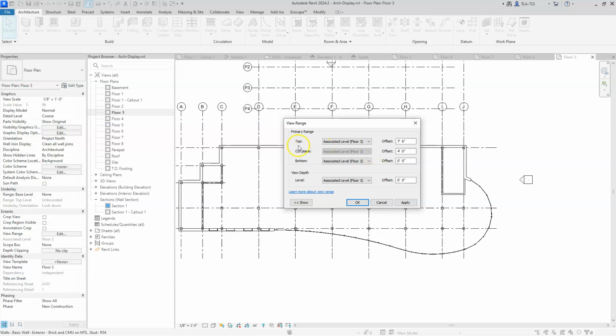And for example, if we have something that we want to see that's up high in a plan view, whether it's a window that's up high on a wall or something that's down low, we need to make sure that our view range allows us to see that thing. Vertically, we're going to be in a position where, or you can think of it as a camera, our camera's in a position where it can see the whole range that we want to see.